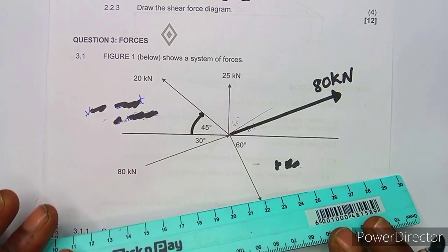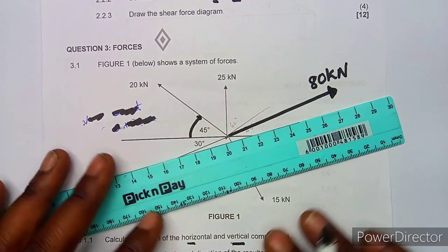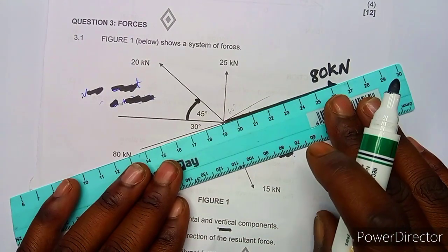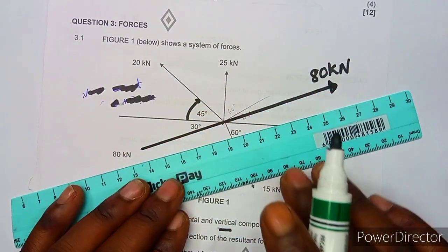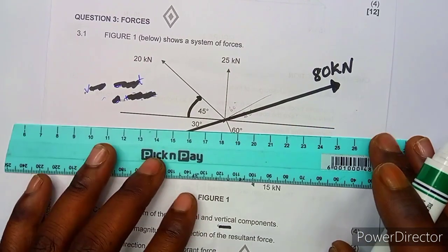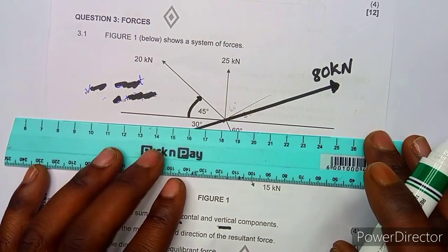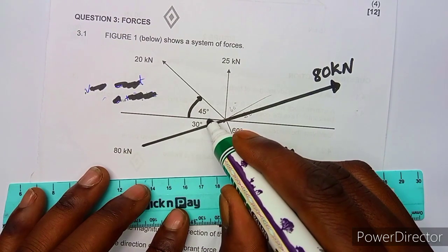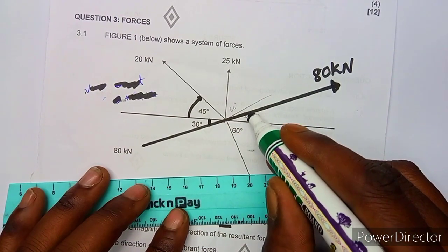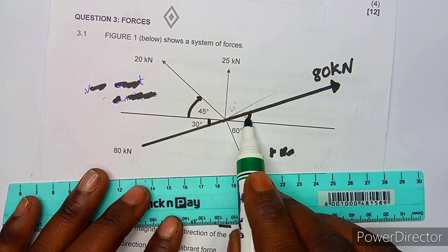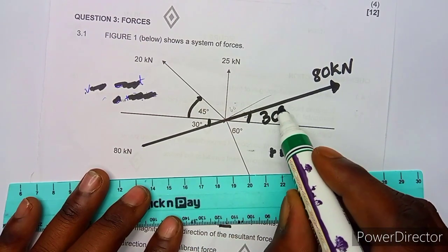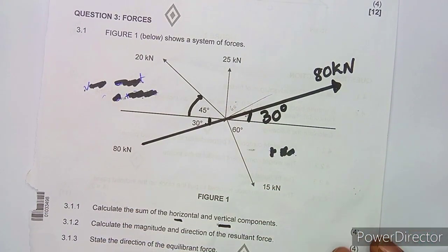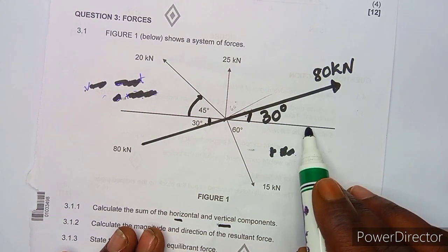But what is going to be the angle? Let's consider this, guys. This line here is actually a straight line. From this point here, we have taken a straight line, and this one also, we already have this horizontal line. So these are actually vertically opposite angles. So this angle and this angle are equal, from vertically opposite angles. So if this angle is 30, it means this angle is also 30. So there's an angle of 30 degrees in between the force and the horizontal axis.